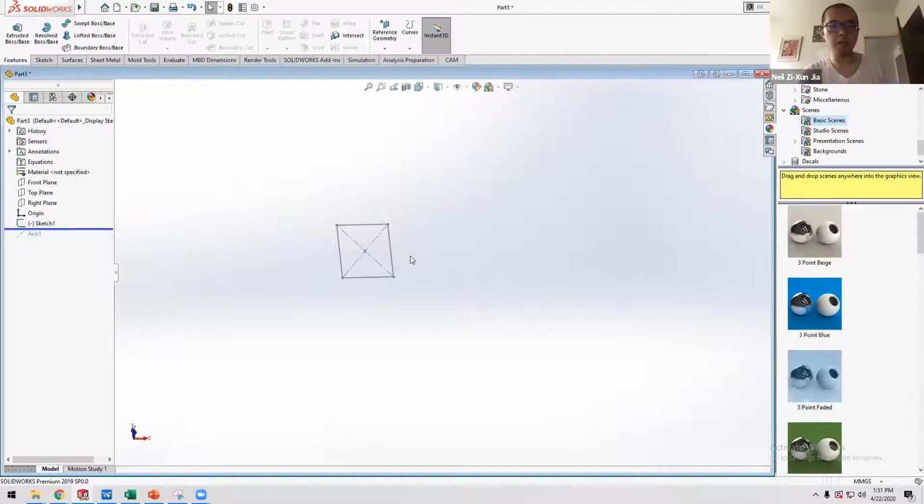I see. So this leads into the order of operations being important in SolidWorks, leading to the best practices for modeling: you should create all your positive features first, then make all your extrude cuts, and then make all your fillets or chamfers at the end. Because you may change something about your model, which will break because the features that you've created after were referencing something that no longer exists. I see. Yeah.